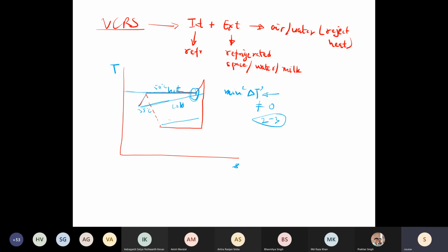Similarly, in the evaporator side also, the refrigerant need not exit exactly at x equals to 1, that is saturated vapor. It can also undergo some amount of superheating. So this is not the useless superheating which occurs between the ambient, that is outside the refrigerated space. So this is still occurring within the refrigerated space only. So that is your indoor side or your freezer segment. Okay. So again, over here also you can have such a limiting case.